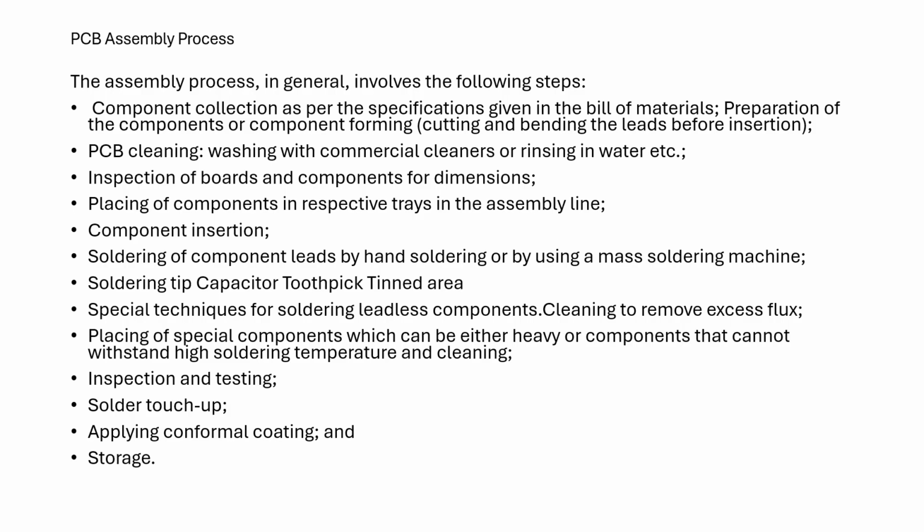Here are the following steps: the component collection as per the specification given in the bill of materials, preparation of the components or component forming, PCB cleaning, washing with commercial cleaners or rinsing in water, then inspection of the boards and components for dimensions, component insertion, soldering of component leads by hand, soldering by using a mass soldering machine.